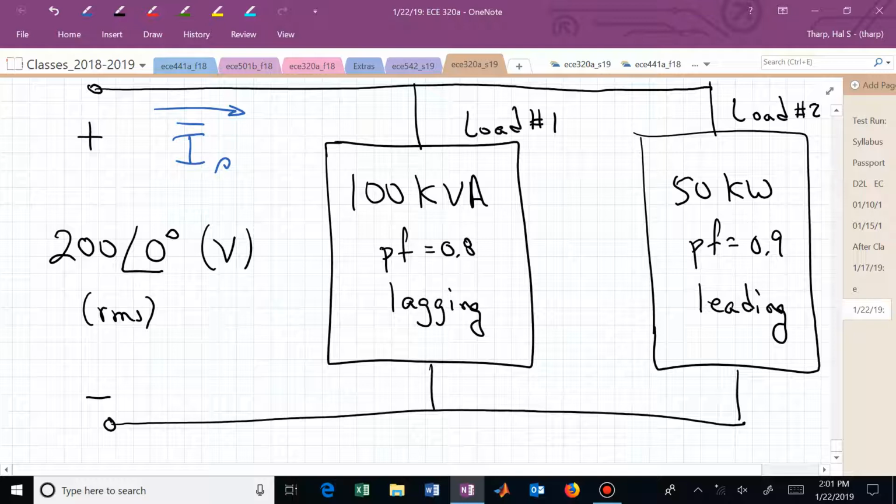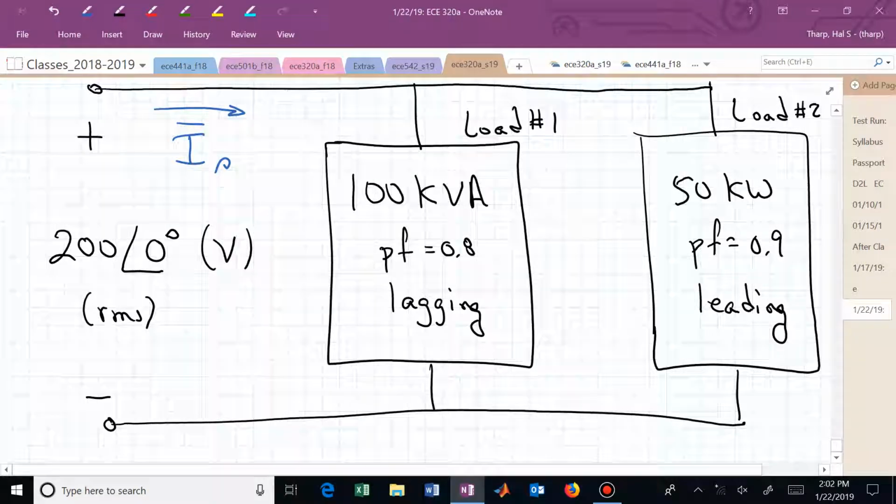And the strategy that we had before we can use again. In the previous example, we simply found the total complex power, and then from that we were able to back out from our complex power expression this current I sub S. Let's try that again, except now we're not given these load powers in terms of these orthogonal components. We're given mixed, different quantities.